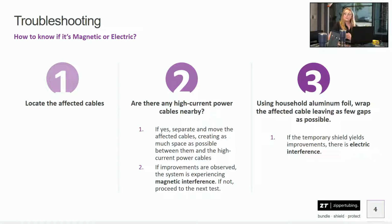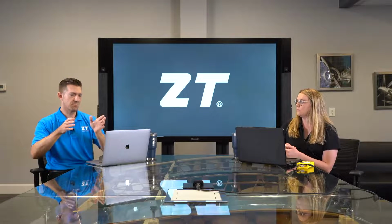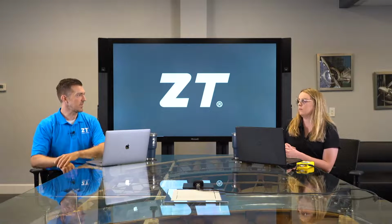Right, and you say, more distance the better. What are we talking about here? Is this a couple inches? Are you talking yards? How far should they look at? Typically, to start, I recommend even a foot, 2 feet. Gaining a little bit of distance is going to knock down that interference if it's magnetic. So do what you can. If there's anywhere where those cables can't be separated and they do have to cross, cross them right at 90 degrees, and that will cancel out the field. But if you are seeing improvements, then it's likely that you're dealing with magnetic interference.